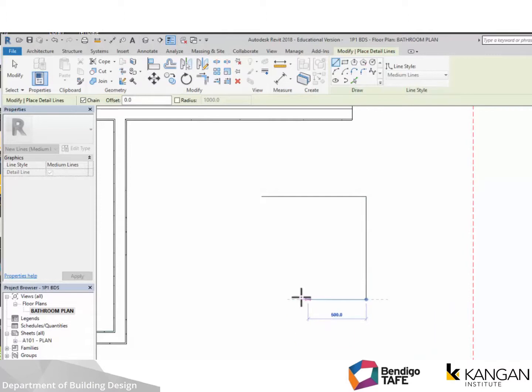So we now can bring in the next side of our box across. Again, Revit's dropping a line down. It's seeing what the other line is up the top there, and it's saying, maybe you want to go there. So there's a lot of predictability that it's doing for us, and we can use those tools. By picking there, we've set that next 900, and then we can go back to the start again, and you'll see the end point is popping up again as what's called a snap.